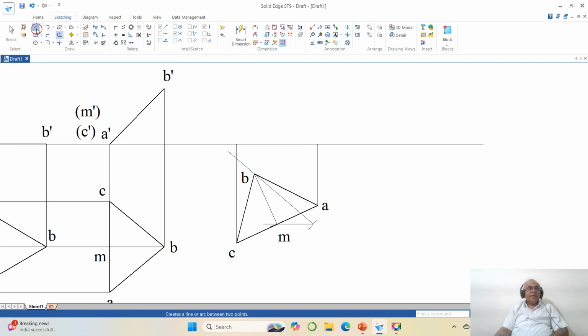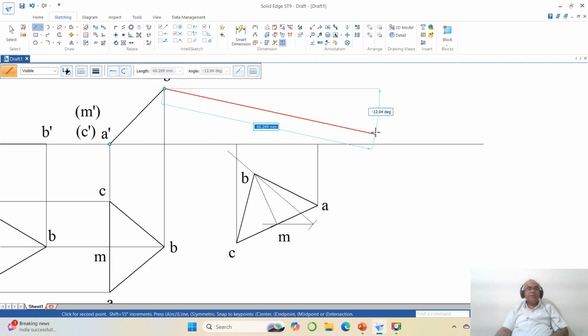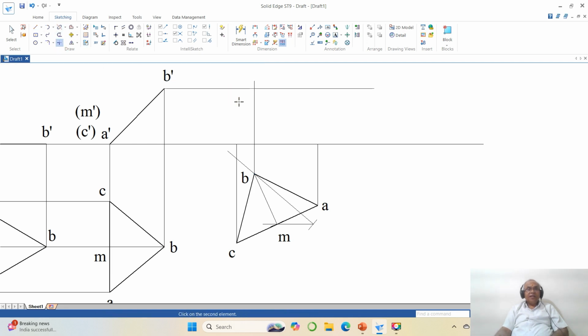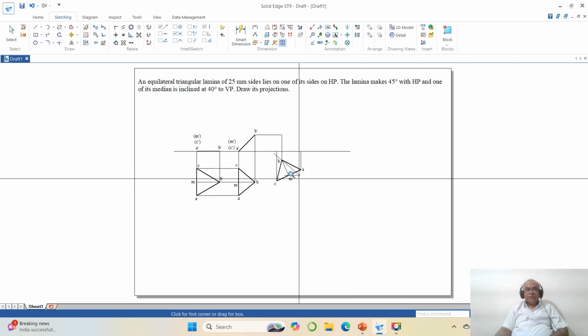Similarly, draw a line from the end point of this to the horizontal direction. Then similarly from B, you take this and draw this. Then go to trim corner between this line and this line. Now we need to go to fit. Then go to zoom window.